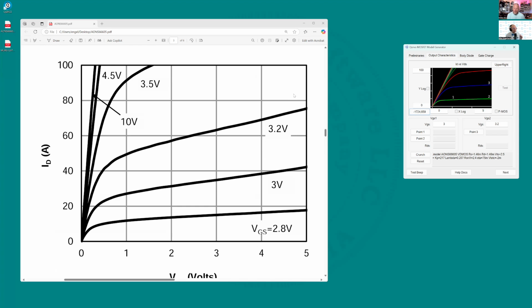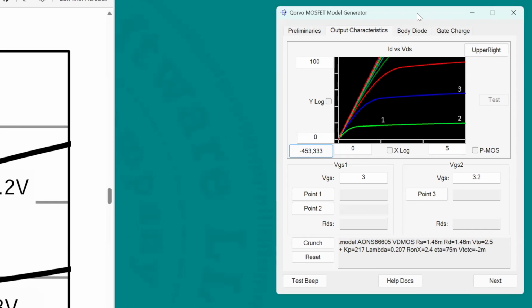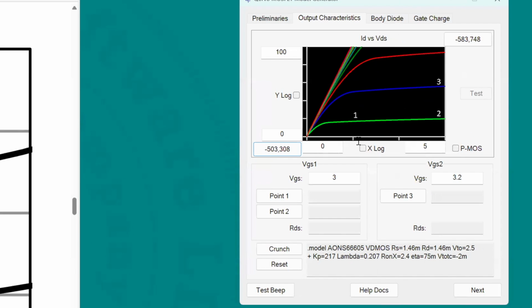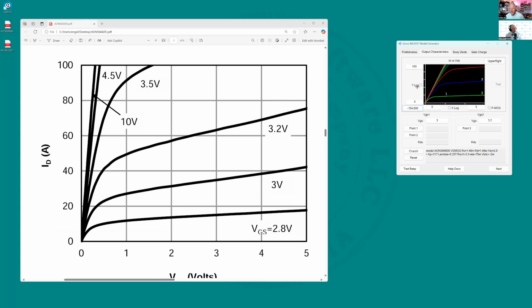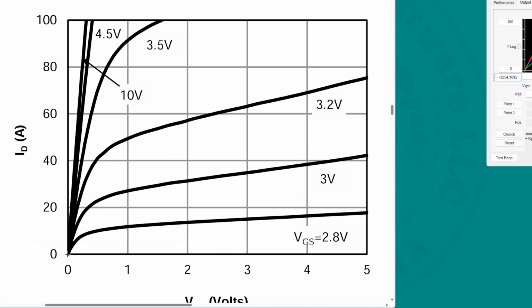So I want a crosshair cursor. What I do is I point at this application, and I just messed things up. I have to cycle through this. I'm going to start over. I point at the application, and I press the mouse button down. Now I have a little crosshair cursor that will XOR with the pixels on the screen, and I keep holding the mouse down, and then I can move over to the PDF, and I still have my crosshair cursor, and I point at the pixel I want. It's XORed at exactly the origin, and I release the button. So the digitized point is when you release the button, not when you do the mouse down.